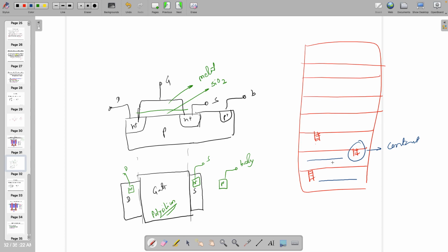However, if you are connecting, let's say this is, assume that this is metal 2. I'm calling it metal 2 because it's available. Let's assume that it's on the second floor of the building. And same metal 2, if we are passing through here, same metal 2 line, then there is a direct connection. It's short circuited.